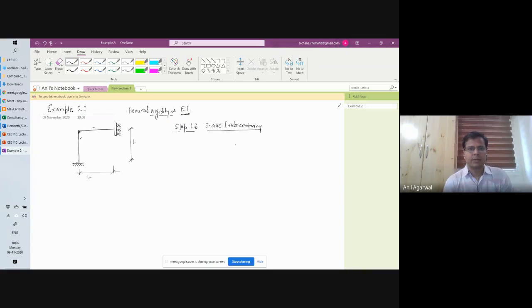All right, so for static indeterminacy, since this is a frame system, I use the expression for frames, that is R minus 3N. Here R represents all the unknowns. Since this is a frame system and I don't see any special complications within it, I can assume it to be a single system, so I will take just the boundary conditions here. If I had to split it into two parts, then R would change accordingly. But for now, R is equal to 3 here, and how many reactions am I getting here? Two reactions, right?